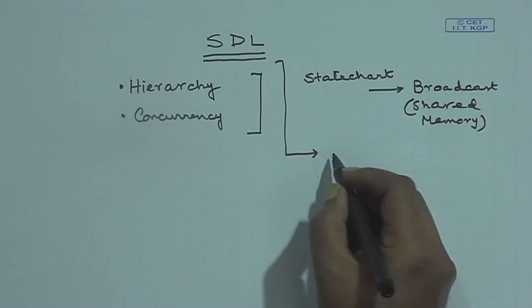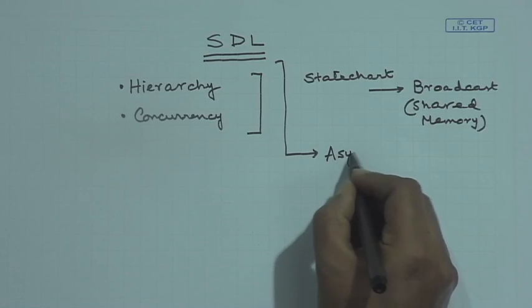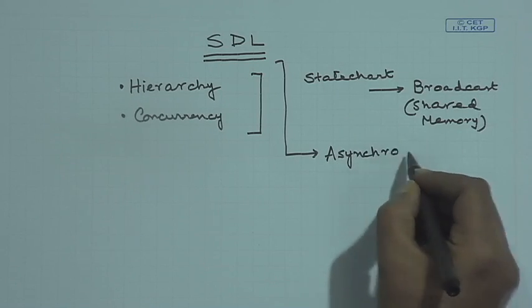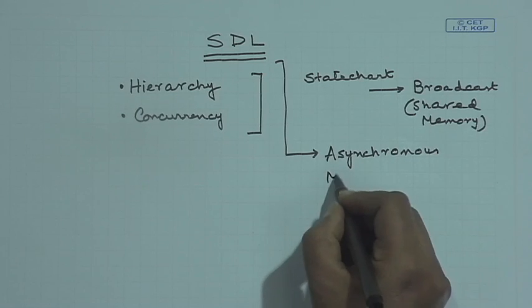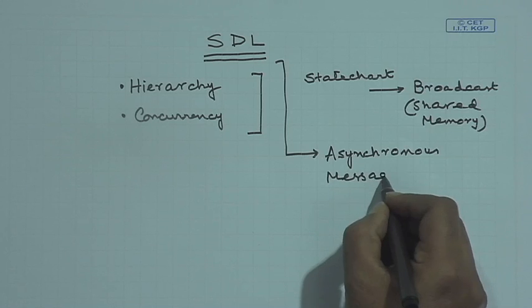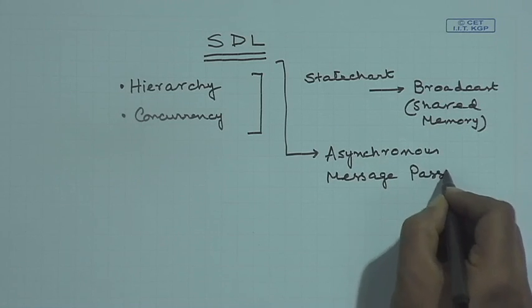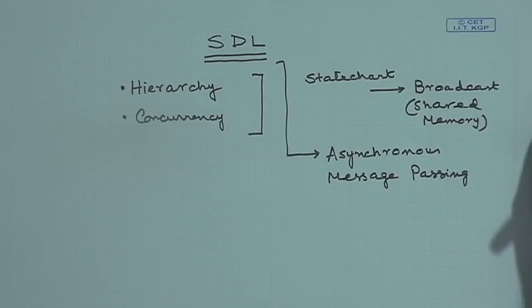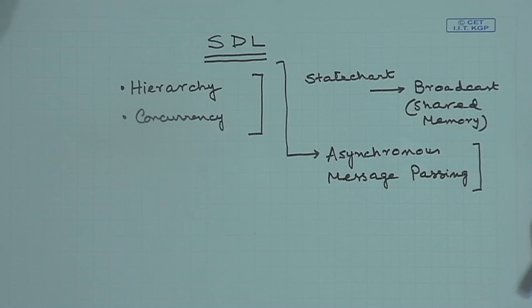You know that there can be two types of communication, one is message passing, another is shared memory. So, here we take recourse to asynchronous message passing. SDL was initially developed for telecommunication applications historically, but then has migrated to other embedded system synthesis as well.